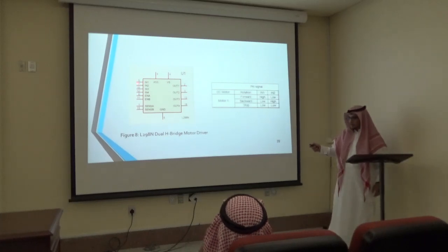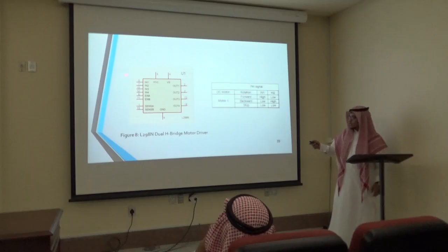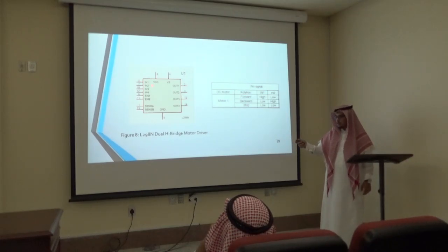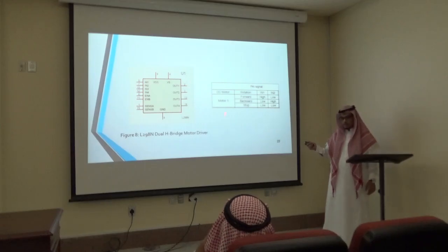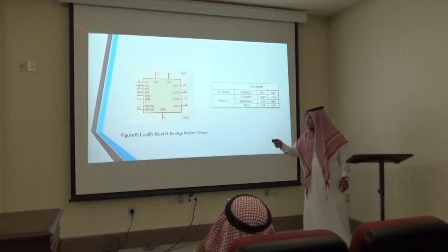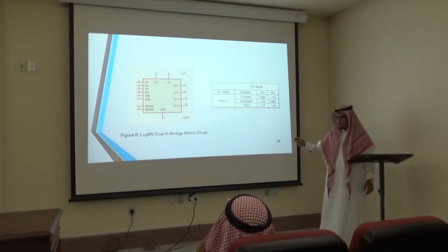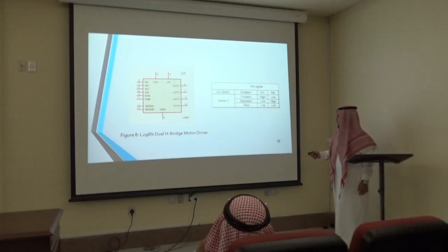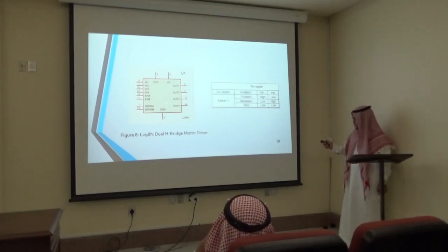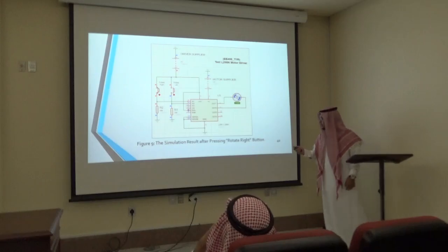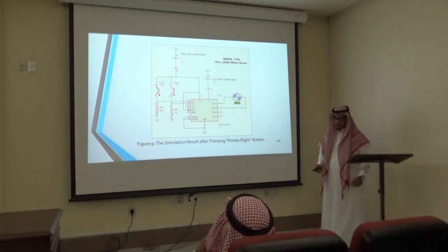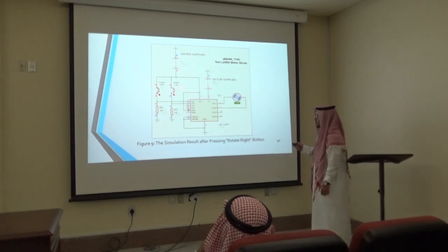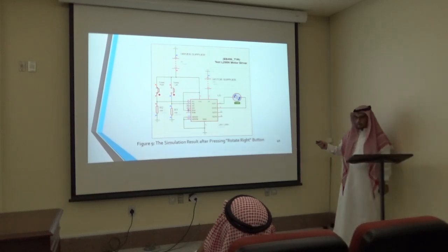The output depends on the IN1 and IN2 pins. If we give logic one to IN1 and logic zero to IN2, the motor will rotate forward, and if we give the opposite, zero to IN1 and logic one to IN2, the motor will rotate in reverse, as you see in the table. Now this circuit was built using the Proteus software. As you see here, there are two push buttons, the motor driver, and the motor.